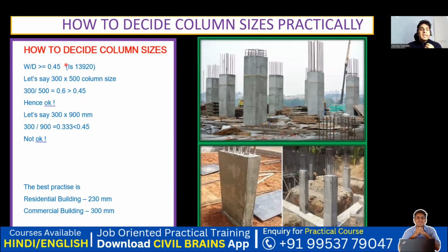That means if I take any column, let us say a column size where 300 is the breadth of the column, and when I say 500 mm, that is called the depth. So this is the depth of the column, and this is the height of the column. Don't get confused. When I say depth, it means the vertical portion in the drawing. The longer one becomes my depth and the shorter one becomes my width. Pretty simple. Now we'll apply that width by depth ratio.